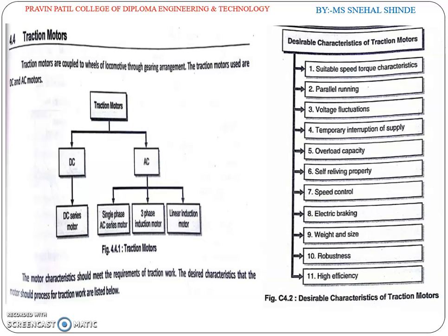The arcing produced on the commutator surface may extend over the whole periphery and flashover may occur. This is to be avoided at all cost. Thus, motors should be capable of taking the heavy loads without flashover.